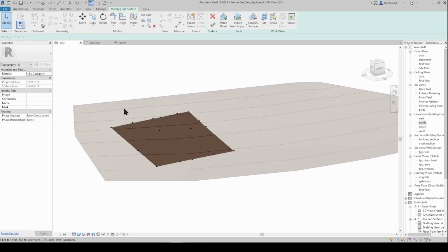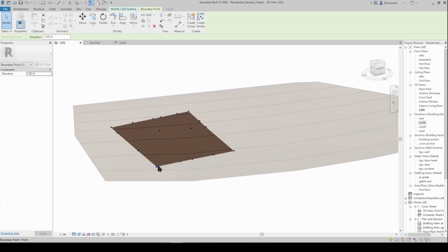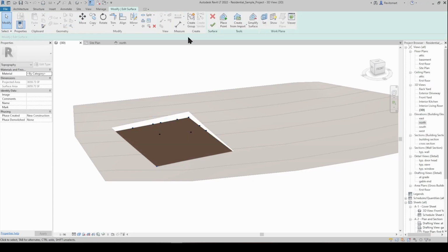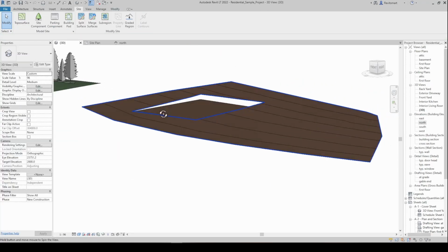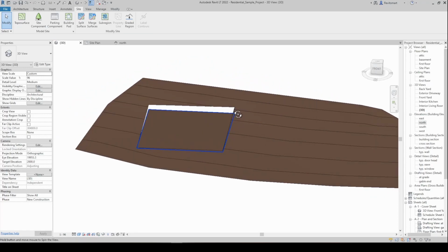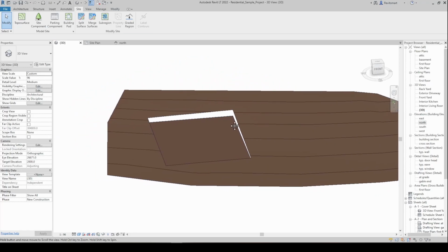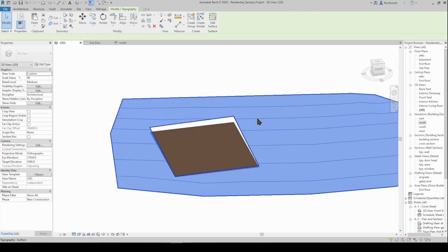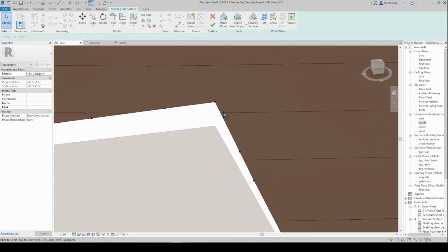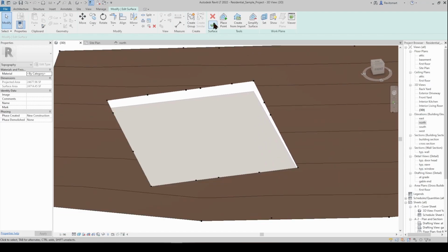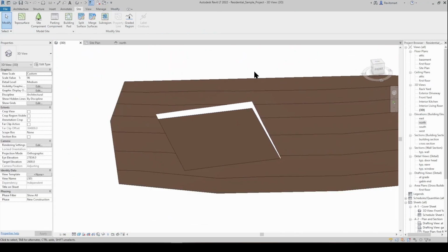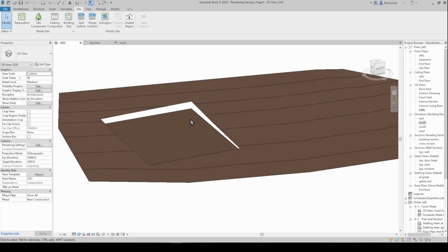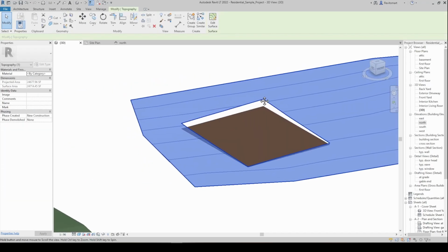So if we want all of this to be, let's say, 1200, then we can. That's essentially what the building pad tool does, but with less control, and it's just a bit more fiddly. And then we can also modify this and split this further. I highly recommend the video that's going to be upcoming. Can't recommend it at the moment because it hasn't been made, but yeah, the split surface tool is a great tool, which is very important to get your head around.